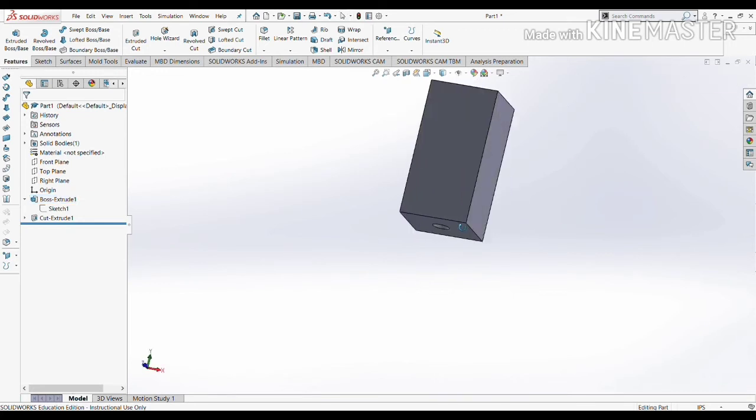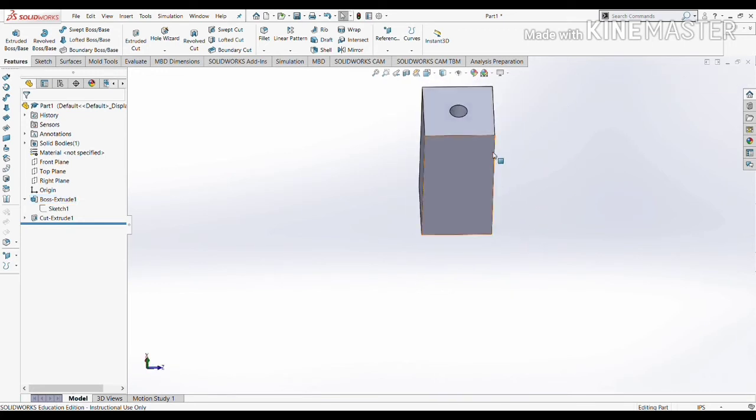Okay, so moving on from this is going to be the first part that we've made. So that's just a quick introduction to the extrude and the extrude cut, which can be really, really useful tools when you're designing square parts, or I mean even round parts. If you want to make the thing a shaft and you want to put a hole through it, extrude and extrude cut can get you pretty far without really even needing to know the other parts of SolidWorks. However, they can be pretty inefficient. So there's some things they really don't do well. But how about some other tools that will do those things well?